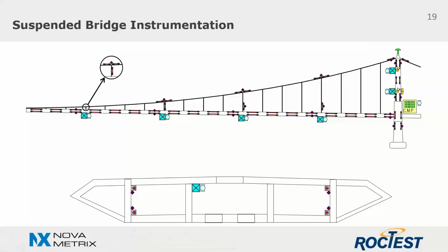Therefore, one cell with parallel topology is installed at the base of the pylon. And also here, tilt meters are used on the top of the pylon to measure the rotations in both vertical planes, and also at the base of the pylon to provide redundancy.